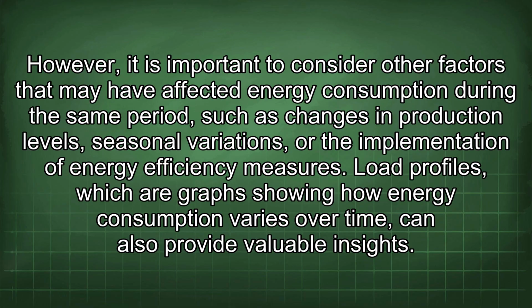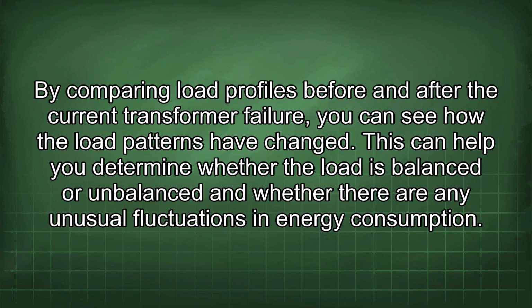Load profiles, which are graphs showing how energy consumption varies over time, can also provide valuable insights. By comparing load profiles before and after the current transformer failure, you can see how the load patterns have changed. This can help you determine whether the load is balanced or imbalanced and whether there are any unusual fluctuations in energy consumption.